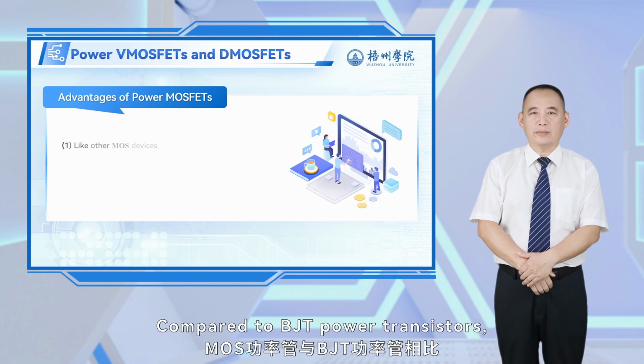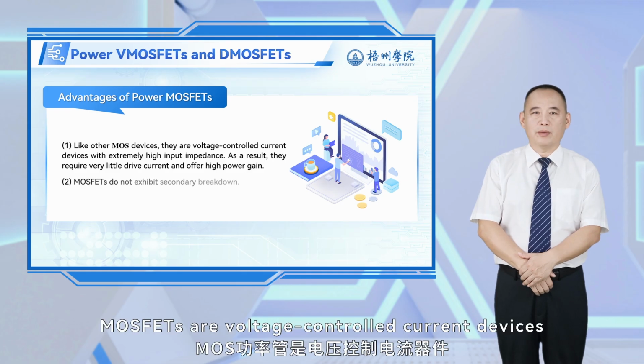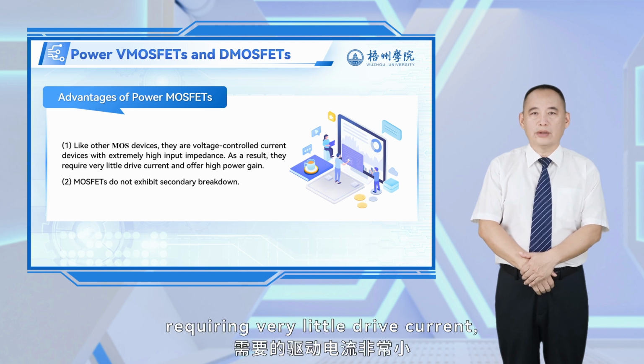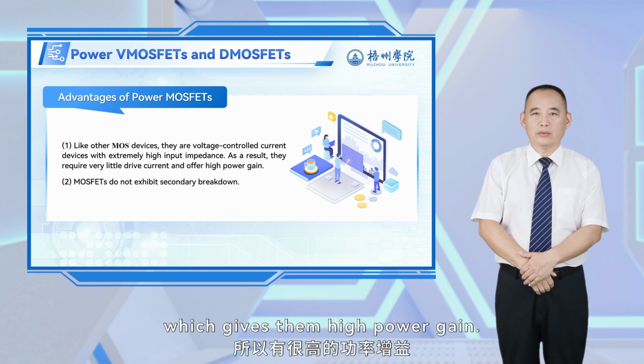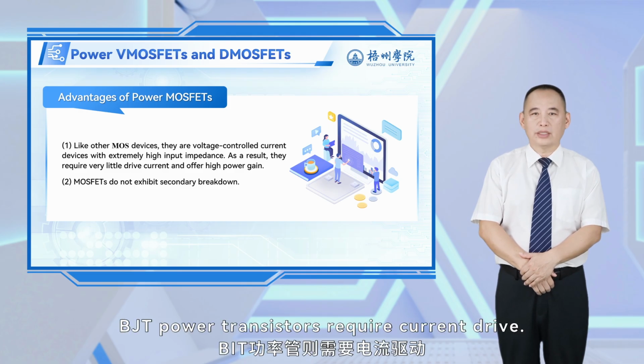Compared to BJT power transistors, MOSFETs offer many advantages. MOSFETs are voltage-controlled current devices with extremely high input resistance, requiring very little drive current, which gives them high power gain. In contrast, BJT power transistors require current drive.